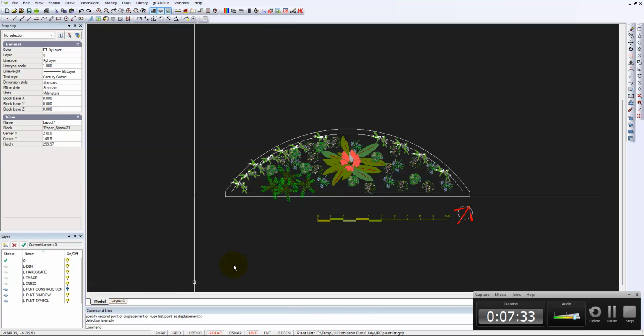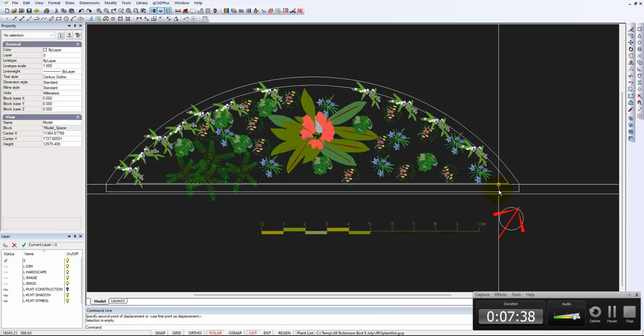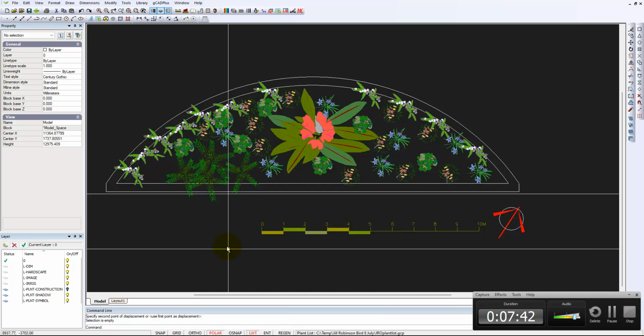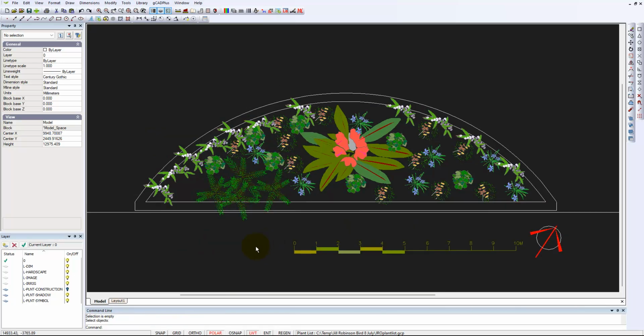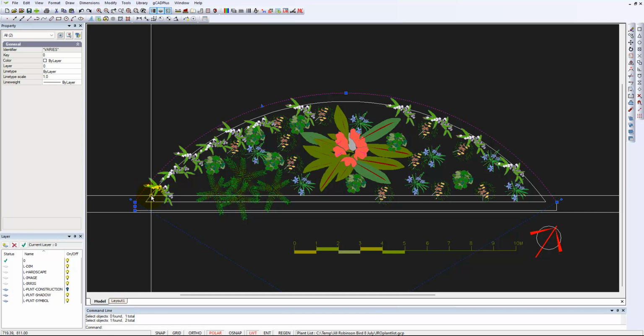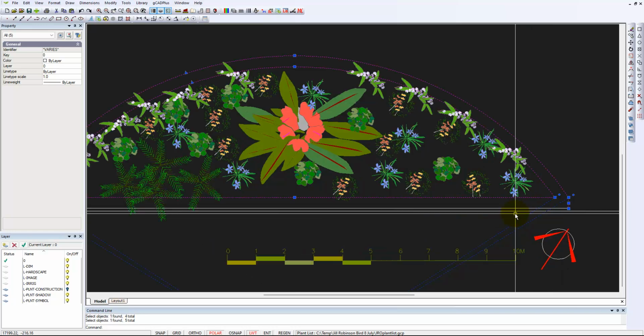I mentioned that we might see if we can give some texture to this dry stone wall. That's done with what's called the hatch command. If we're going to hatch an entity, it needs to be a closed entity. And we showed earlier in this series that if we pick, say, an arc, and notice I've got the single shift on, so now I've changed that, and I should be able to pick the two arcs, the horizontal line, that little bit at the end, and then the base.